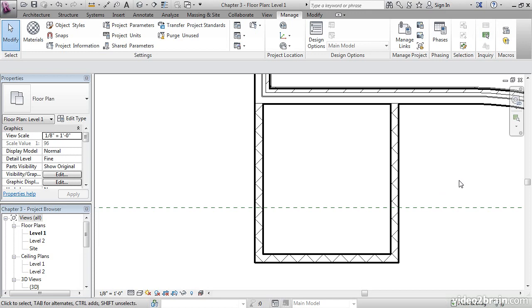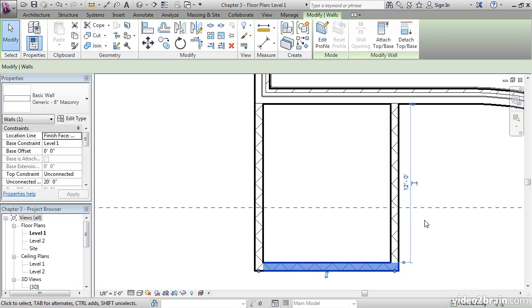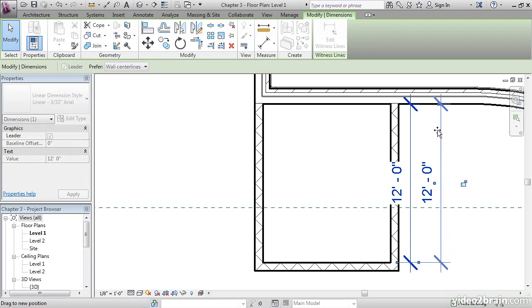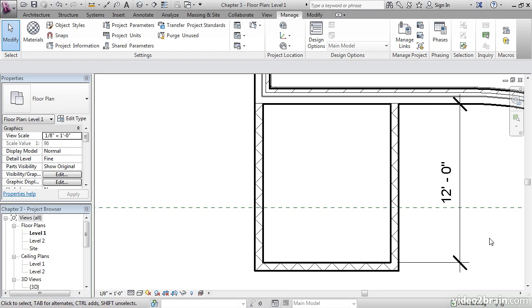Click OK. Let's do the same thing to the wall in the south here. I'm never sure if it's the right dimension, so go ahead and select it, and of course, it's not. All you need to do at this point is click into here and type in 12 and hit Enter. One really cool thing about Revit is, once you see this temporary dimension light up, you see this little dimension icon. That's called Make This Temporary Dimension Permanent. Go ahead and click that icon and click off of the wall. You'll see 12 feet in there as a permanent dimension now. If I hover over this and select it, I can actually physically hold down my Move button and move it out from the wall. Hit Escape a couple times to clear out of any command.